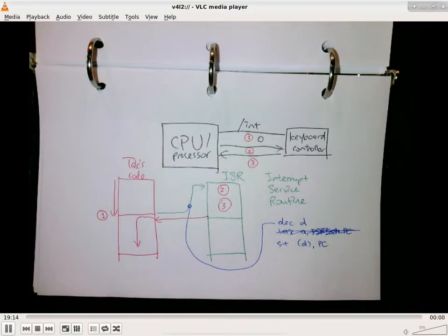And that is also the reason why we decrement the stack pointer first before we store. Because if you store first, then you can potentially cause a problem. Whatever you store can disappear. But if you allocate first by decrementing the stack pointer, you basically say, don't touch this. If at that point an interrupt happens, it's still okay. Nobody's going to touch that location that you just reserved. And then when the ISR returns, you can go back and fill that location with whatever content you want. Is this okay? It is kind of abstract because there are many things going on at the same time.